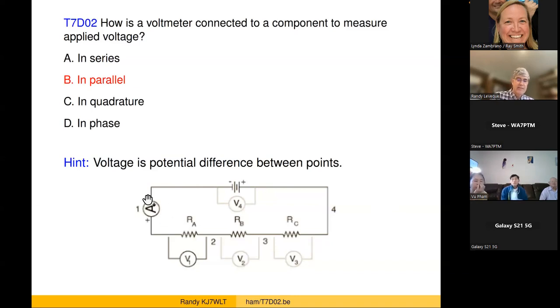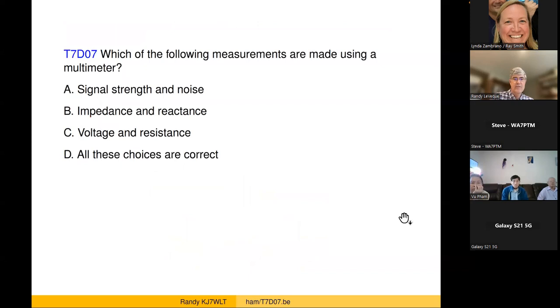By contrast, this little A device up here is an ammeter, which is in one of the future slides, and it's shown connected in series. So the ammeter, which measures the current flowing through this circuit, you actually have to put in the circuit in such a way that the current has to flow through it. The only way you can measure the current flowing through here is by putting the ammeter in series here. But the voltmeter, you can just touch the two probes to 2 points on the wire, and it will tell you the difference in potential between those 2 points, the voltage between those points.